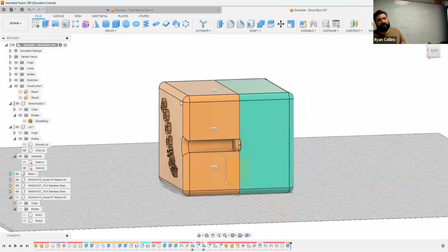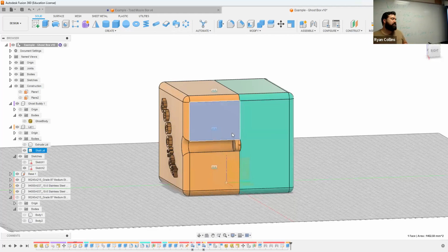Now, a different way of approaching this would be something that's an actual little latch, some sort of actual little hook that connects around and actually locks onto something. Well, there's a lot of different ways you can approach that. But in this case, all it needs essentially is something with a little bump, a positive protrusion from the base, and just a little latch from the lid, because we're going to make use of the fact that we're printing in plastic, and plastic is kind of flexible. So I can have something that moves over that bump by flexing a little bit.